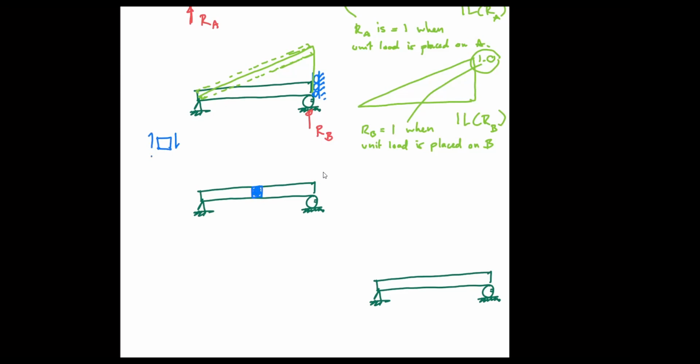If I look at this piece, if I allow the shear to go free at midspan, the shear is now on the right, correct? So it's going to be this downward shear. You see, the positive shear here must be downward.